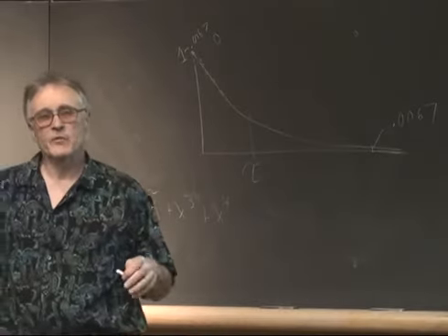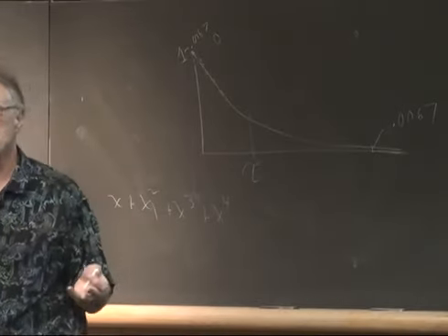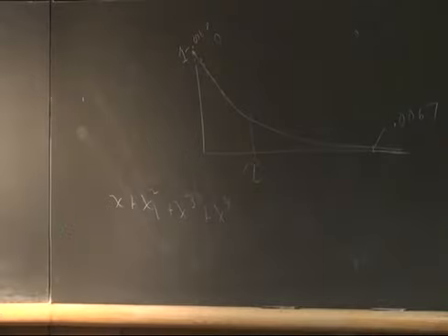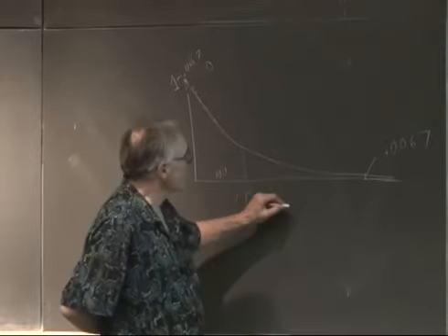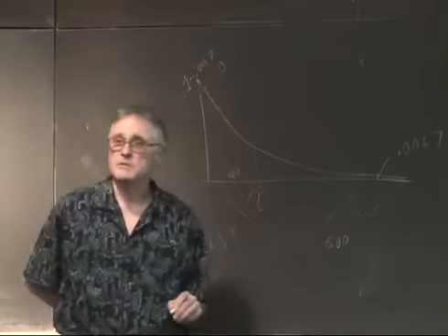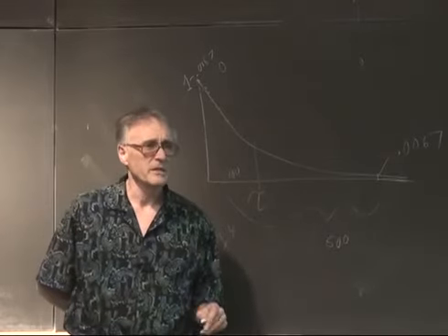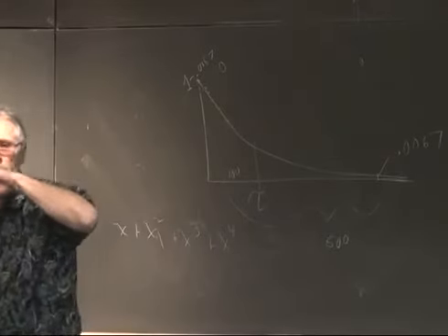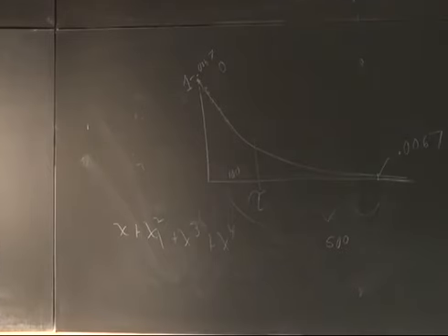And that says that if we want to have no more than a 1% change in the amplitude between steps, we need about 100 steps per time constant. So this will be about 100 steps. If we go all the way out here, then that's 500 steps. That's okay. That's an okay sized table. Not too small, not too big. It's decent, reasonable.